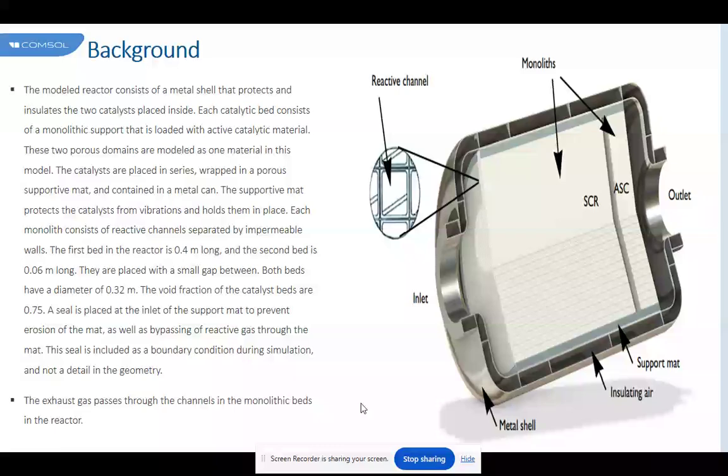It is reasonable to expect that a result from using a combination of two cell densities would be obtained from the interpolation of the results from both cell densities individually. However, the simulation has demonstrated with a theoretical model that a combination of cell densities in a single monolith can lead to a conversion efficiency lower than that obtained when using either of the two cell densities alone. Let us refer to that as unbounded efficiency.